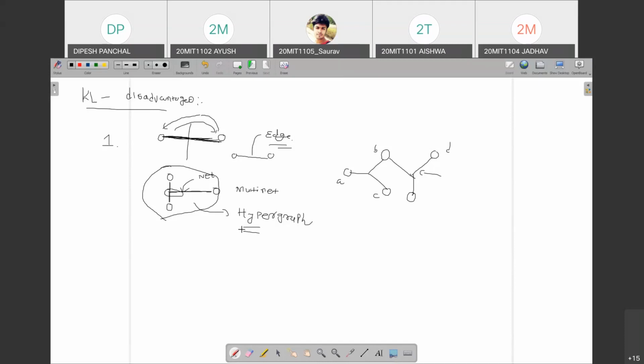So that is one problem in this. Sir, which Boolean expression circuit can be represented by a hypergraph? Like in the previous example, we have a number of NAND gates, so we represent it in a graph. So which type of circuit? Yeah, I'm saying any digital circuit we are definitely representing with a graph. But interconnections are very important in physical design. We are not going to touch what is available inside this NAND gate. So we represent it with vertices or nodes, all these kinds of nodes.